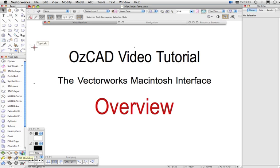If you hover over a tool, either a tool set or a tool icon, then you will get the name of it plus the keyboard shortcut that will activate that particular tool. If while hovering over a tool you also press the command key, then you will get an explanation of what that tool can do. So holding down the command key, I can move up here and I get a longer description of what that particular tool does. If I release the key, then I'll just go back to getting a description of the tool itself.